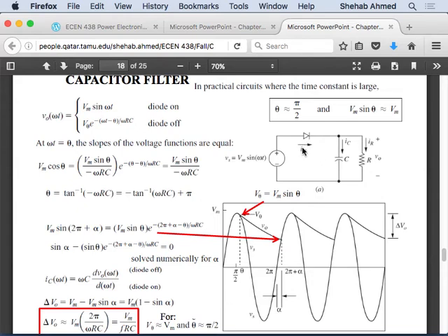If I make the charging occur more frequently, does the slope of discharge change? Where did we get this slope from? This is an exponential, right? Where did we come up with this equation for this exponential? From the RC circuit, right? So the RC is the same.